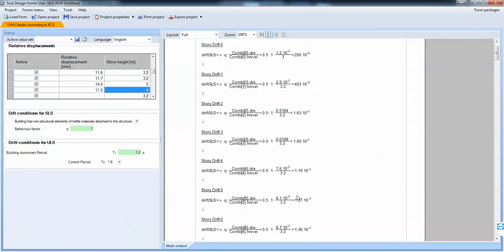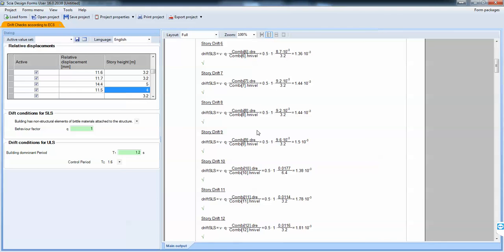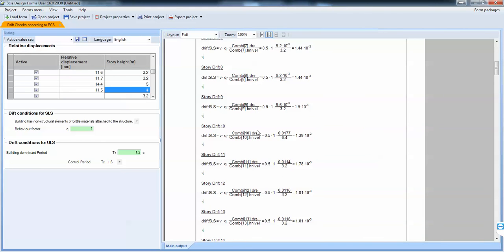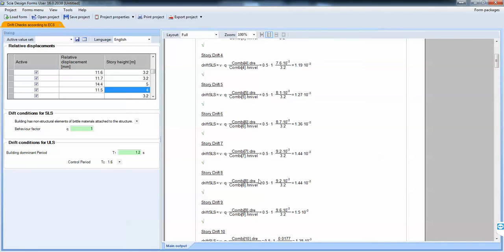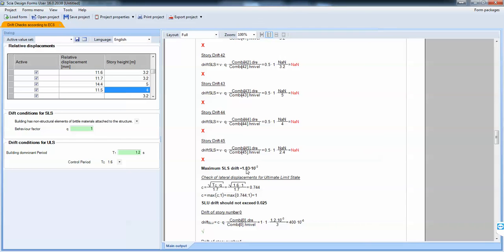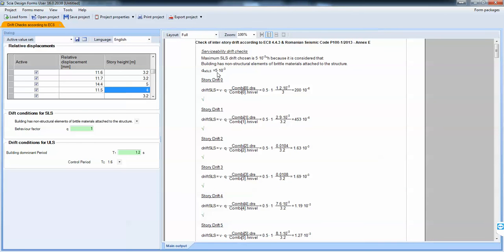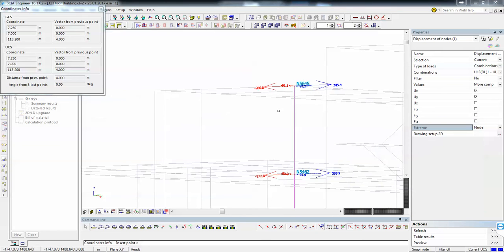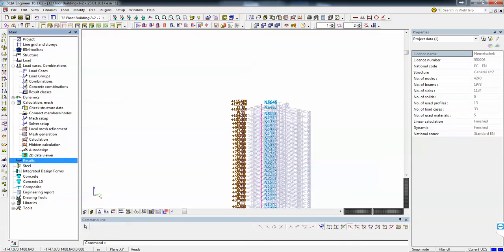Okay, so basically everything is okay. The 3.2 levels had no jump, everything moved smoothly, and also the taller levels are okay. So the maximum drift for whatever I inputted is 1.83 as a comparison with 5. So we have a lot of capacity. It's no problem from lateral points of view. So the building has enough lateral capacity. I'll hit save here.